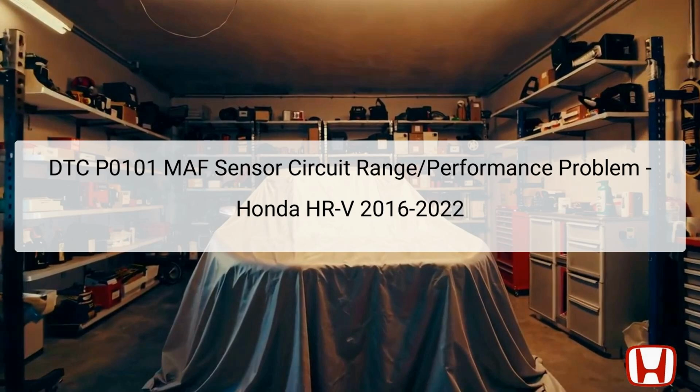The MAF sensor is typically located in the air intake duct between the air cleaner and the throttle body. Proper diagnosis and repair are essential to restore normal vehicle operation and avoid further complications. Before beginning troubleshooting for DTC P0101, ensure that any related DTCs, such as P0106, P2228, or P2229, are addressed first, as they may contribute to this issue.